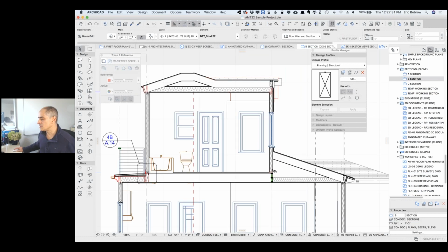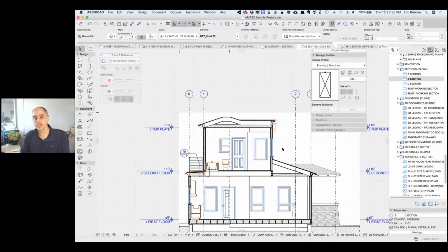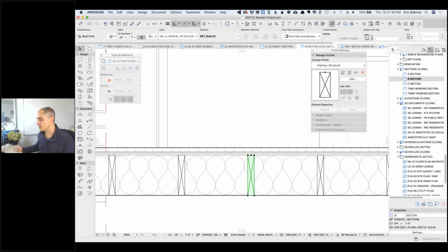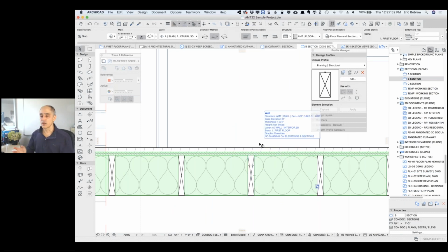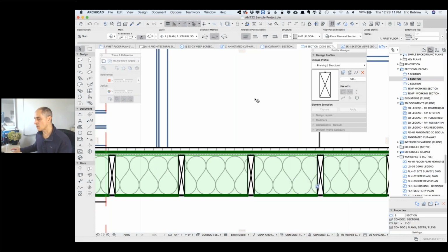So in the sample project, I carefully illustrate how you can model in 3D. For example, all of these elements here are 3D in the larger volume, and they automatically cut through the insulated space there. Now, another thing that took a while to set up, and frankly, the Graphisoft template does not do a great job on all of these things, is to get the line weights. So this is looking at it in hairline or just a clean single line thing. If I switch to true line weight, we can see what's going on here.